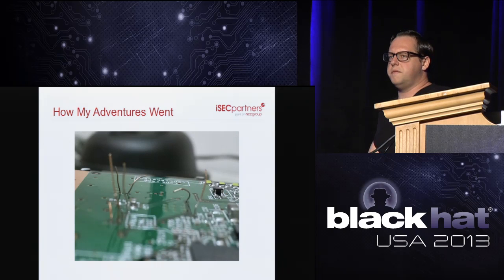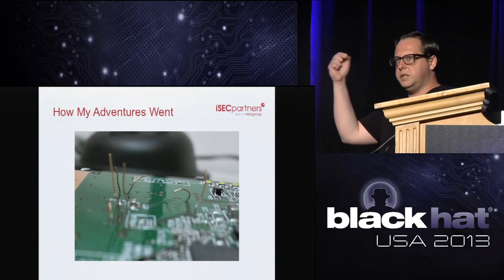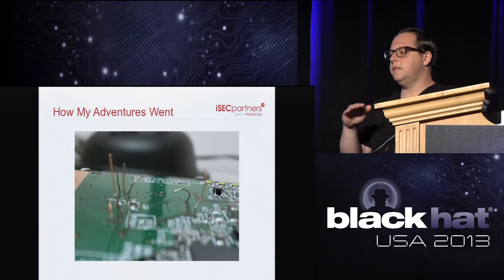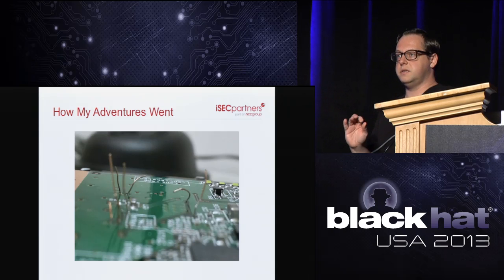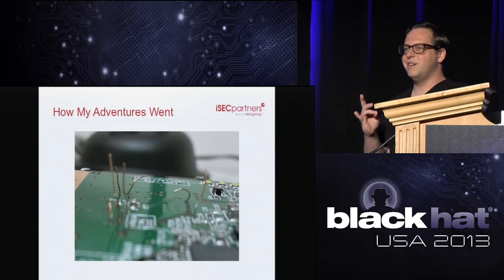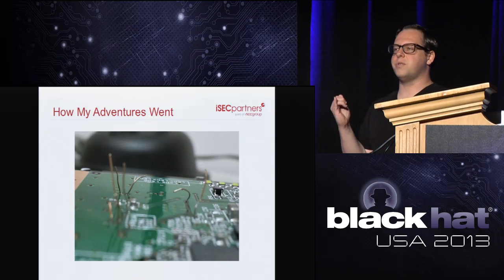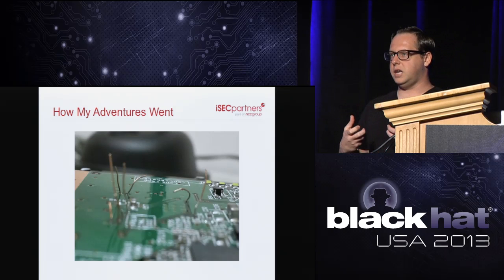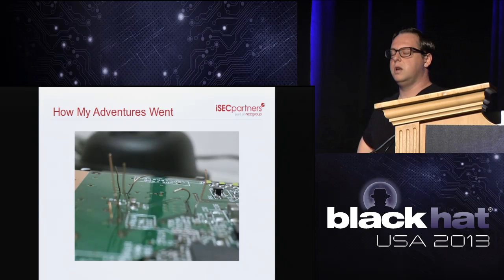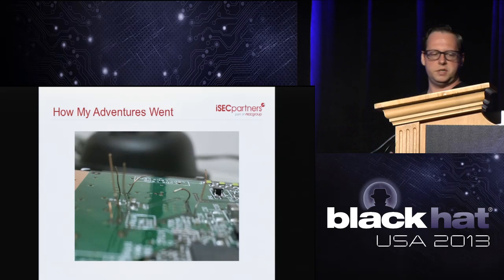This is an image of these lines being soldered into vias. These are strands of Ethernet cable being soldered into vias. Another great use for the epoxy, we can take these wires coming out. They're very delicate because these are very, very small things we need to be soldering. And trust me, take it from my experience, these are really easy to rip out with a logic analyzer. So there's tension on the logic analyzer probes. When you hook them in, if you're not careful, it could pull on those wires and potentially cause damage to the entire board. You have to throw the whole thing out. So the epoxy really helps to put that layer over there and protect this stuff while we're sniffing.